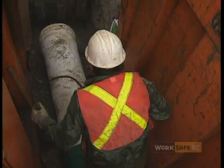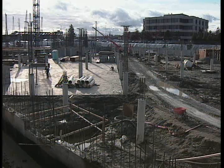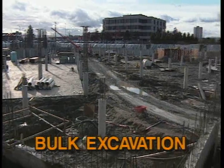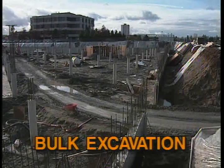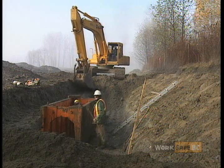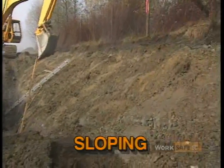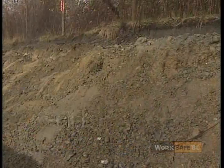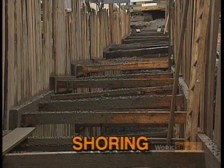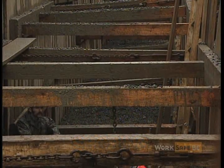The first step in understanding safe excavation work is to define the terminology. A bulk excavation refers to excavations wider than 12 feet, such as basement excavations. Sloping, a system where the sides of an excavation are flared to a safe angle. Shoring, a support system designed to keep the sides of an excavation from caving in.